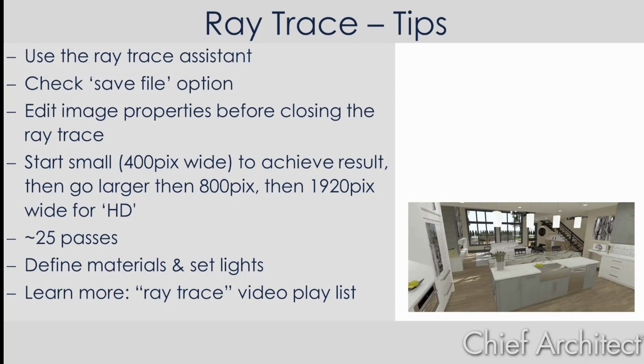That's pretty big. Then set it and typically let it go for at least 25 passes. That's very subjective. 25 passes, it depends on the room scene and how much light you have going on in it, because in this small little scene you see in the lower right hand section of my screen, the light can be bouncing all the way through that room, and it can take a while. That's also a function of how fast and powerful your computer is.